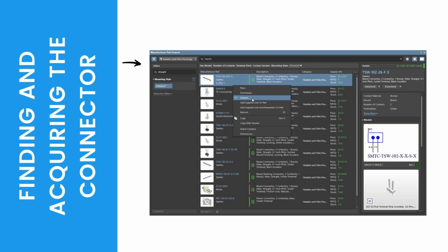Seventh, in the Create New Component dialog that opens, select the connectors component type and click OK. Eighth, in the Use Component Data dialog that opens, disable the Only Matching option at the top right of the dialog and enable the parameters, symbol, footprints, and datasheet options, and then click OK.